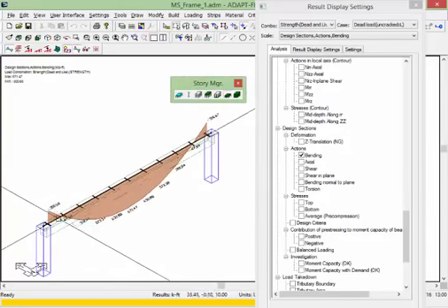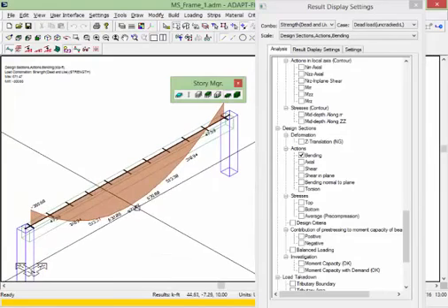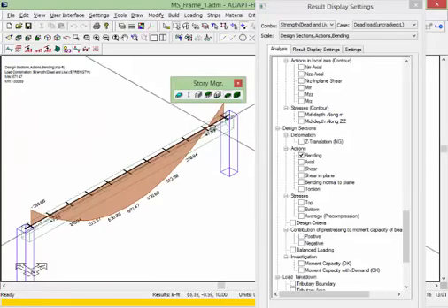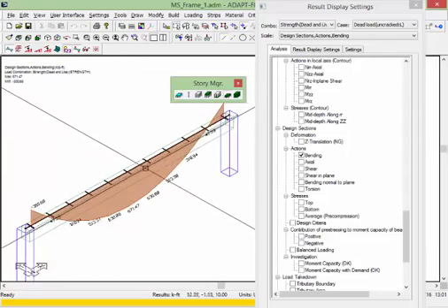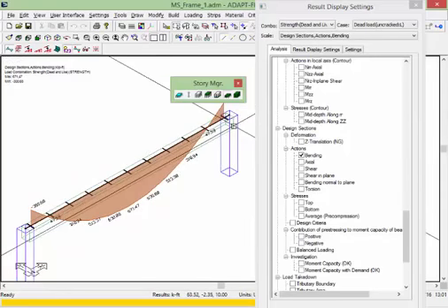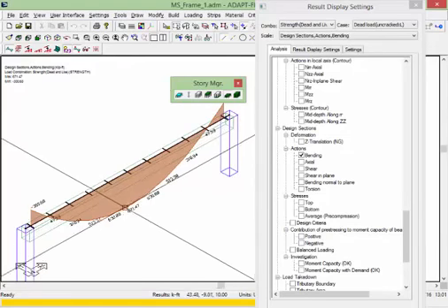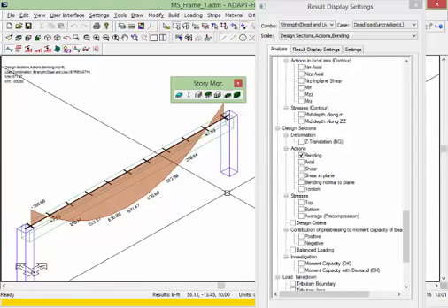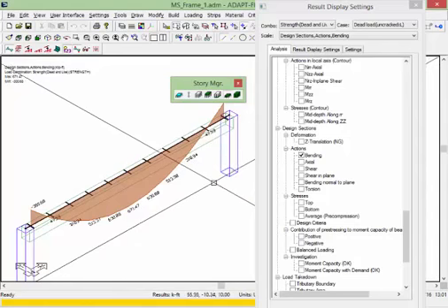Now there is a case that the results don't exactly match, and that's simply because the discretization of the frame elements and the increment of distance between frame elements may not align perfectly with the increment of design cuts. So in other words, you're interpolating between two nodes along the beam frame element, but they're close. So these particular values for design sections now, not beam moments, but design section moments can be designed for.